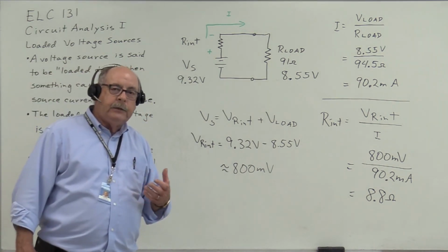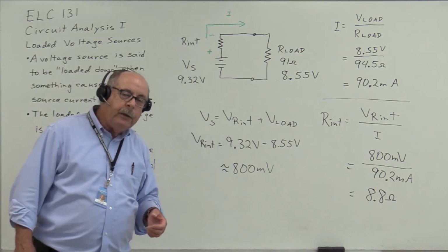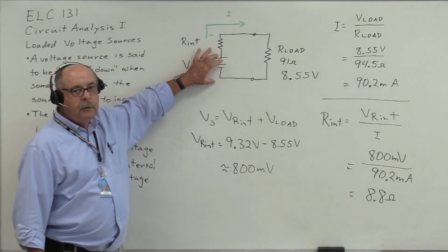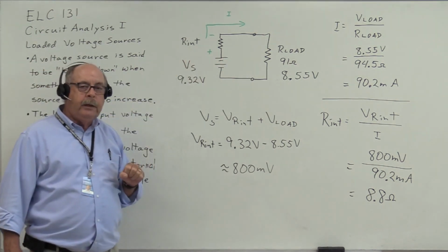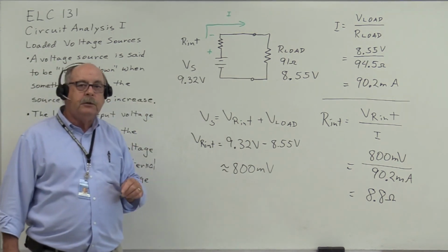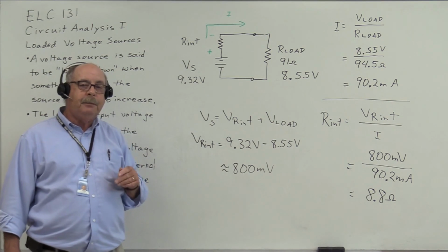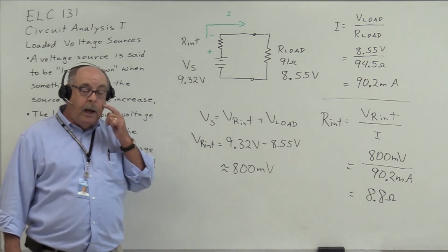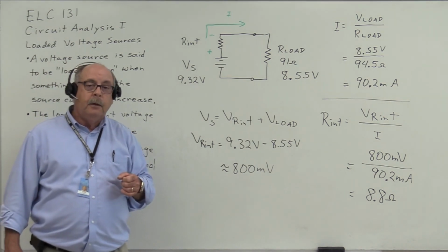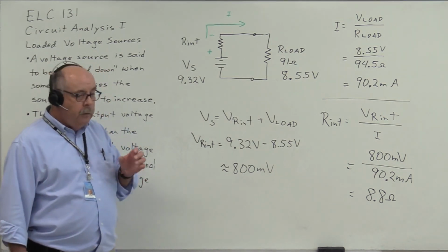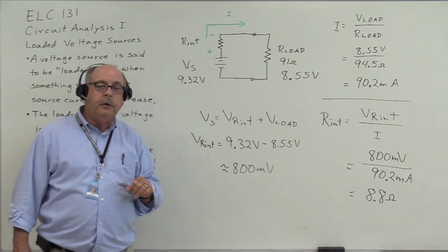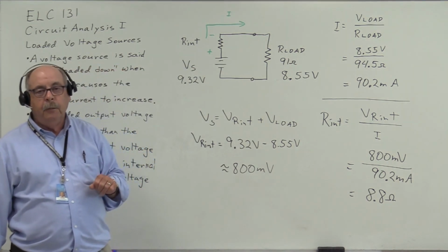When a battery gets weak, it's not because the battery has lost some of the chemicals inside of it. When a battery gets weak, it's because of the internal resistance increasing to a point where that battery simply cannot supply enough current to meet the load's demands. So again, you have to place these batteries under load in order to measure them with a meter.